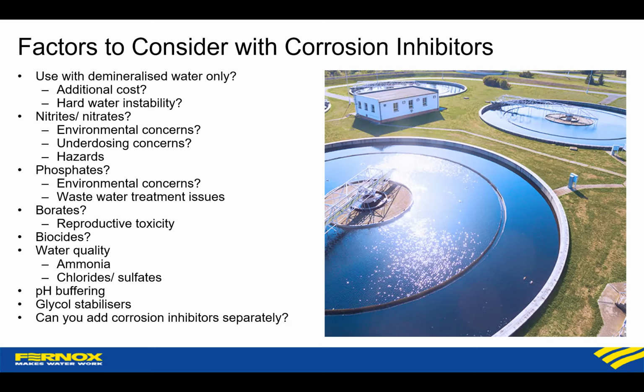pH buffering, mentioned it before, with soft water or DI water. You get any carbon dioxide from the air into the water, that dissolves in and essentially becomes carbonic acid, which then drops the pH, and you'll exacerbate that corrosion happening. So certainly cast iron is not going to last very long in a low pH in an acidic system.